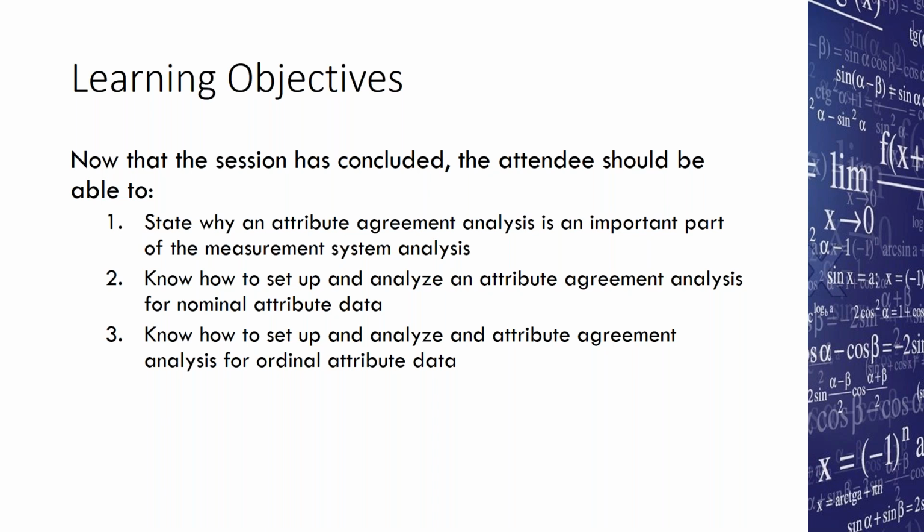The other thing is that if you're evaluating a part and the test itself actually destroys the part, so I think I understand that might be where you're coming from. I think you would want to use the same guidelines that you would have if you were running a variable gauge R&R that is destructive in nature, and that is that instead of working with the same part over and over again, you're working with the same batches of parts instead. So the assumption would be that batches of parts would perform similarly, and that parts within the same batch would perform similarly, but different batches would perform differently from each other. So you would set it up that way if your test itself was destructive and that's how you were assessing it. But if you're just assessing the part after the test, then you would just use this method here that I shared with you today.